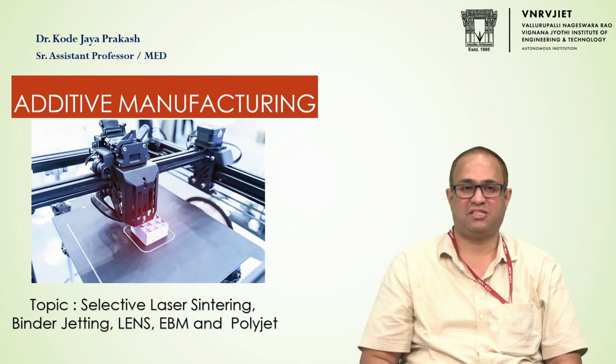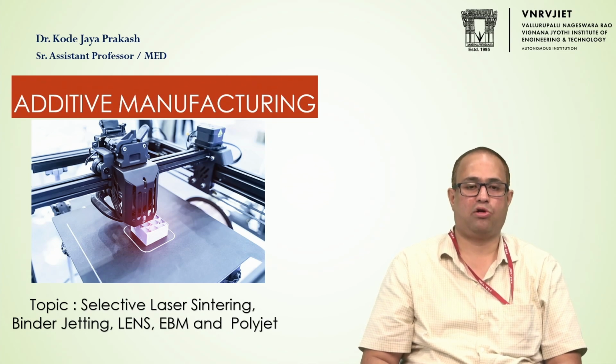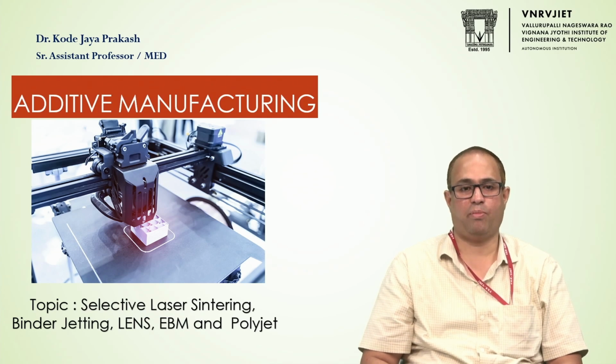Now in this session, we are going to discuss the other remaining additive manufacturing processes: selective laser sintering, binder jetting, LENS, which stands for Laser Engineered Net Shaping, EBM, which stands for Electron Beam Additive Manufacturing, and PolyJet. Selective laser sintering, binder jetting, LENS and EBM come under powder-based AM processes, whereas PolyJet comes under liquid-based.